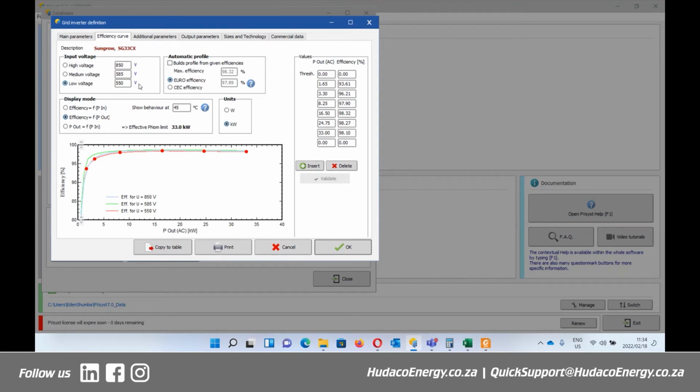If you work exactly with 550, you find out that on a hot day, your voltages will easily go below 550 because voltage falls when temperatures are very high. So you'd probably work with around 600-something volts, maybe 630, 620, so that if it falls on a hot day, you're still within the range of 550.